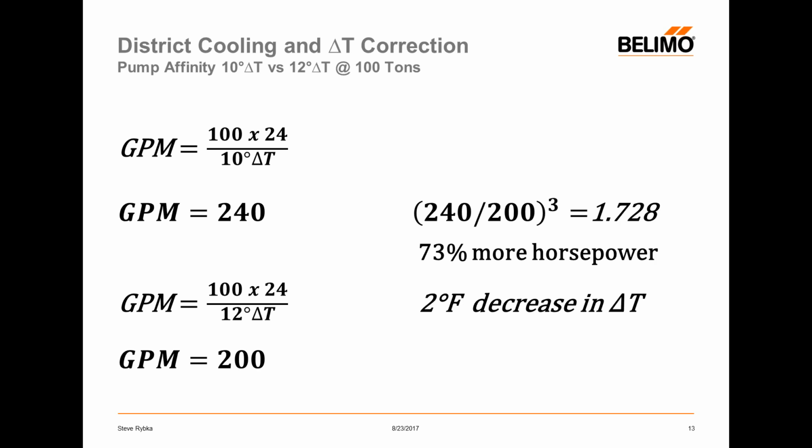So not only can we wind up in a situation where we are paying a penalty based on the lower temperature of the return water, but we also incur more pumping costs. So maintaining proper delta T does one of two things. One, it eliminates your fuel inefficiency surcharges or your low delta T penalties. And two, it ensures that you're pumping as efficiently as possible through your system.